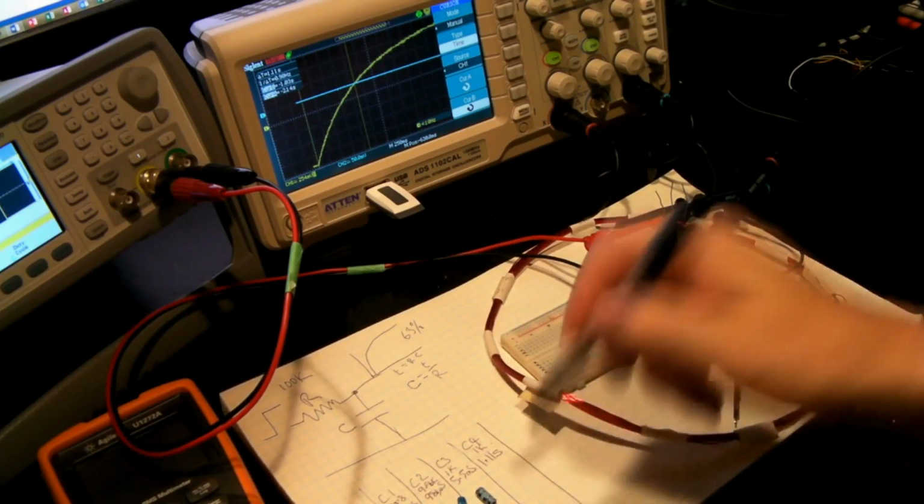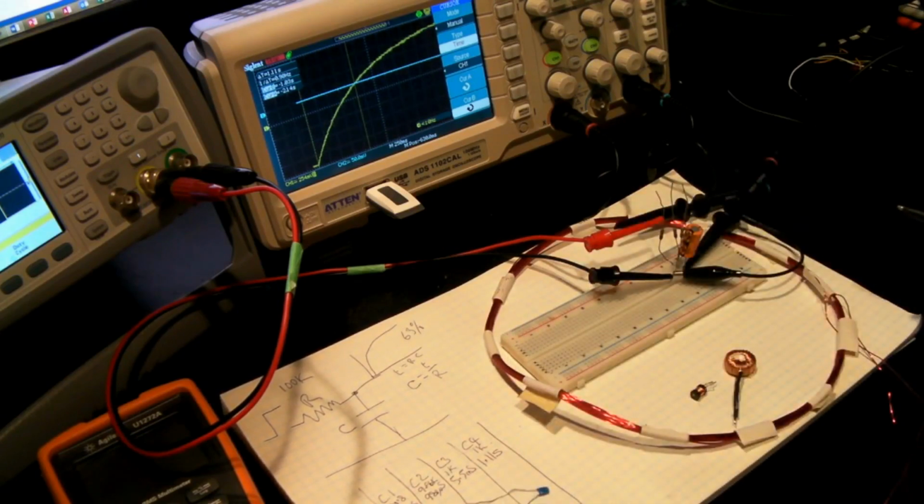Alright. So, how do we know what value these are? Well, we'll do the math in a moment. We're just going to now switch to doing the inductor. So without even knowing the capacitor value, I'm going to do some inductor measurements. And what we'll see is that by having a known capacitor, which we'll actually calculate in a moment, and we'll use an Excel spreadsheet on a screen capture so you can see it, we can then use that by measuring the period of oscillation to figure out what the inductor values are. So now let's just reconfigure this so that we can check inductor values.